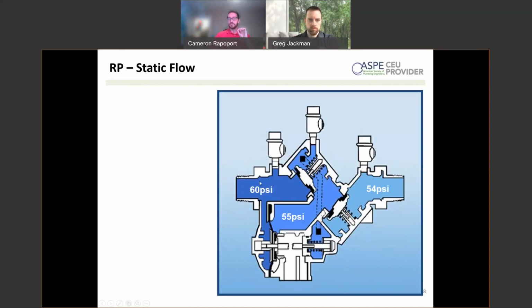So when you hear relief valve, people often think that this is just going to relieve excessive pressure. That is not what these do. These are differential pressure. What it's looking for is that pressure across the first check. So here you see that supply pressure, the inlet pressure, is pushing on a diaphragm. That diaphragm is going to shut the relief valve. And then acting on the other side of that diaphragm are 2 forces.